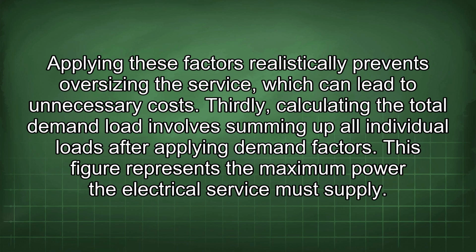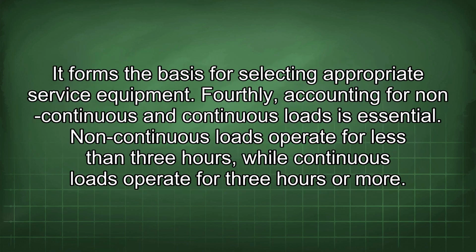Thirdly, calculating the total demand load involves summing up all individual loads after applying demand factors. This figure represents the maximum power the electrical service must supply. It forms the basis for selecting appropriate service equipment.